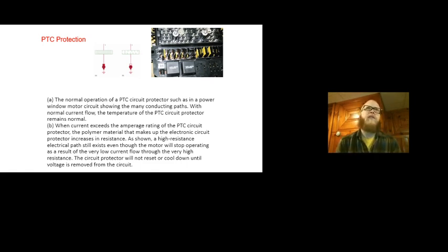You've definitely dealt with this in the engine performance class with things called NTCs, negative temperature coefficient, and that would be something like a coolant temp sensor or cylinder head temp sensor. Those sensors, semiconductors, change their resistance based off of the temperature of the coolant or the cylinder head that they are mounted on.